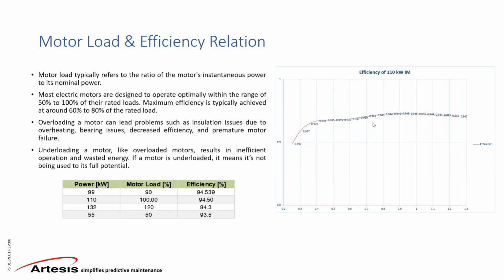And if not, we need to be able to calculate again the cost associated with improper sizing of the motors. But of course, in order to do that, we have to understand this chart and the relationship and how much the efficiency will decrease when the load declines.